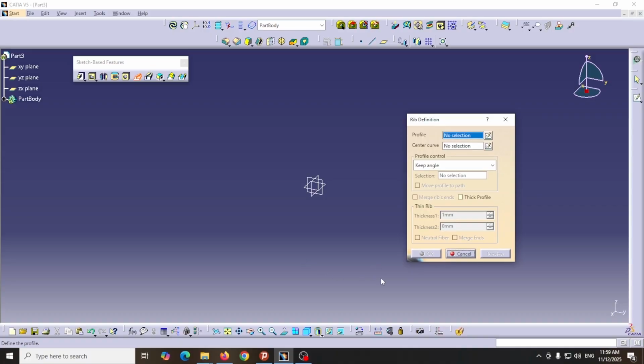If we want the shape of the profile's cross-section to be maintained relative to a surface along the path, we use the third option, named Reference Surface. This is the most advanced control mode and is used to sweep a profile onto an existing solid surface. Application: for designing channels, grooves or edges that must fit perfectly onto another curved surface of your part, and their angle to the main surface remains constant.